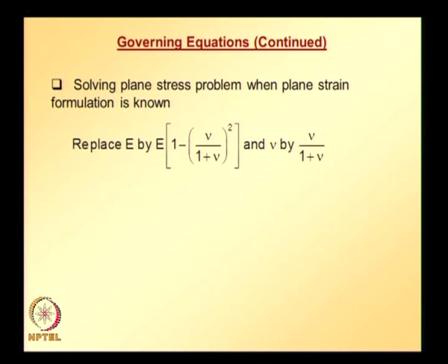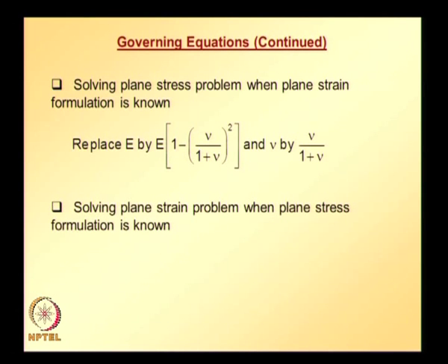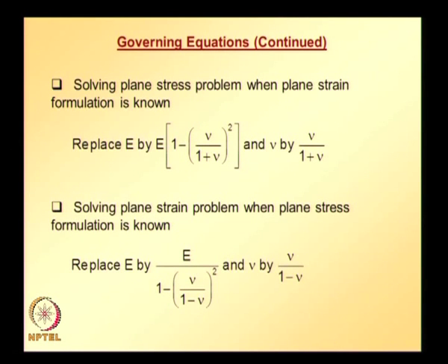So, if the plane strain formulation is known and you want to solve a plane stress case, do this substitution, and for solving a plane strain problem when the plane stress formulation is known, do the corresponding substitution. So, with this understanding of equivalence, if we have either of these formulations, we can easily solve a problem under a different assumption.